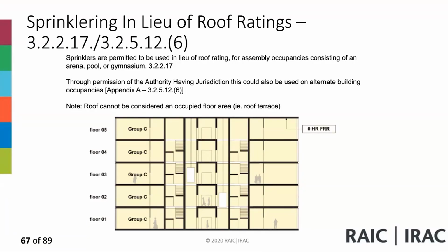In our case, even though it's an exterior floor area, if you have a terrace and you've got seating on it, and people can go up to the pool and have assemblies and events, then you need to be cognizant of the fact that you need some kind of separation of it from the other spaces below, especially if you have different tenants below it.